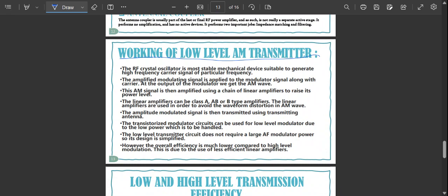The oscillator is a critical stage in any transmitter. It must produce an accurate and steady frequency. You might recall that every radio station is assigned a different carrier frequency. The dial or display of a receiver displays the carrier frequency. If the oscillator drifts off frequency, the receiver will be unable to receive the transmitted signal without being readjusted. Worse yet, if the oscillator drifts onto the frequency being used by another radio station, interference will occur. This is hardly desirable.